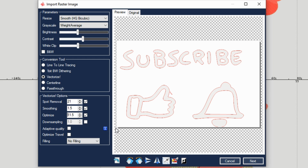A great tool is downsampling. Downsampling will basically correct some of the mistakes. Let's see if we can get rid of this spike here on the thumb up. So let's click on it and let's crank up a little bit. There we go. There you go. So as you can see, we got rid of this spike, but we got again some of the spots. So we can crank up the number and we can get rid of the spots.